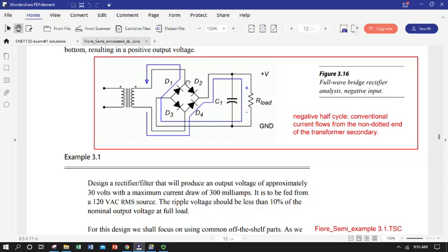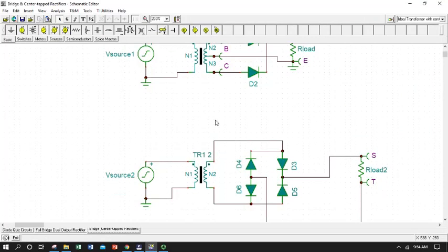Those forward bias voltages are material dependent in the diode, and you don't have a lot of choice in what you can do unless you get a different diode. So if you had a small voltage signal that you needed to rectify, this might be a great use for germanium diodes, which have a smaller forward bias voltage, generally 0.3 rather than 0.7. Good thing we have a lot of components. So we can take a quick look at that on Tina.